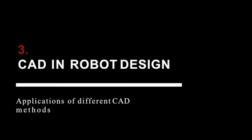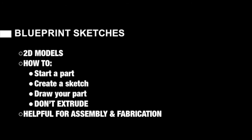Next, let's talk about CAD and robot design. So what applications of different CAD methods can you use? First, there's blueprint sketches. Blueprint sketches are two-dimensional models. To create a blueprint sketch, you're going to start by creating a part. Next, you're going to create a sketch. A sketch is where you draw your part on CAD. But make sure you don't extrude it to 3 dimensions, because if you do, it's no longer going to be a blueprint sketch.